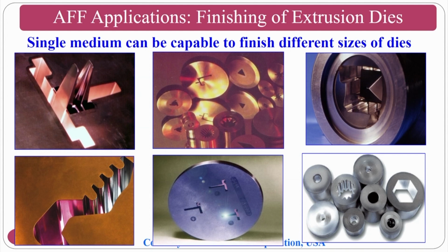Some of the applications, you can see that these are the dies that are generated, simple to complex dies one can generate. These are the various dies for various applications. One can use abrasive flow finishing extensively. The die industry is one of the biggest industries for the manufacturing of many things, extrusion and other things. So, if your dies are not properly polished using abrasive flow finishing process or any other polishing technique, what will happen? Your extrusion pressure requirement will be enormously high. The energy losses will be very high because of the friction if the surface is very rough.